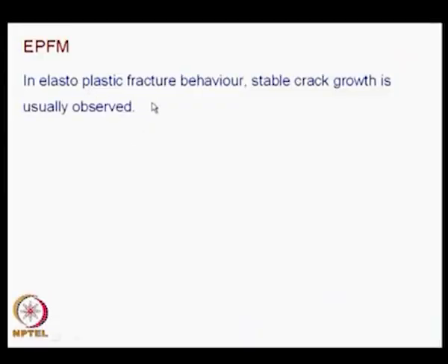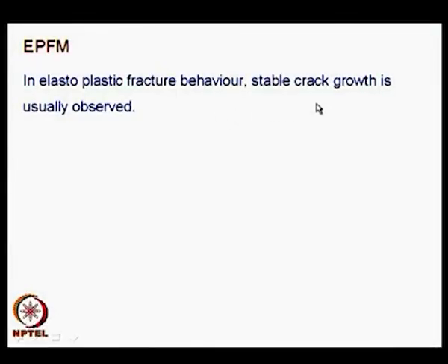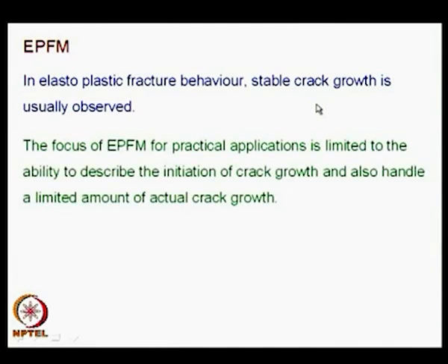In elastoplastic fracture behavior, stable crack growth is usually observed. I had mentioned, when there is crack growth, there is unloading. So, what people have put as their focus in EPFM was, for practical applications it is limited to the ability to describe the initiation of crack growth.